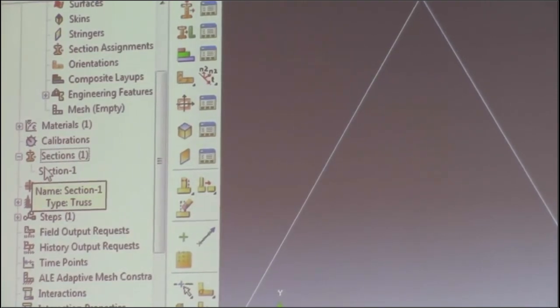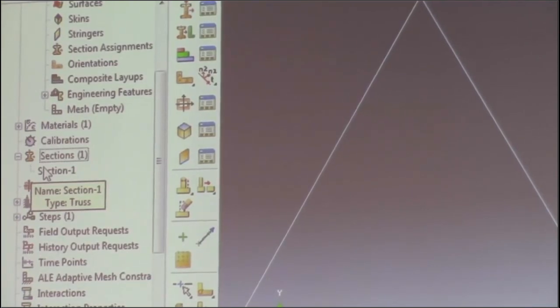Why it doesn't matter? Because if you think about the beam problem, we need... Trusses only have an axial load. And then you only need to worry about the cross-sectional area for stress. Yes. So for a truss, there's only sigma xx, right? And the equation for calculating this sigma xx is F over A.